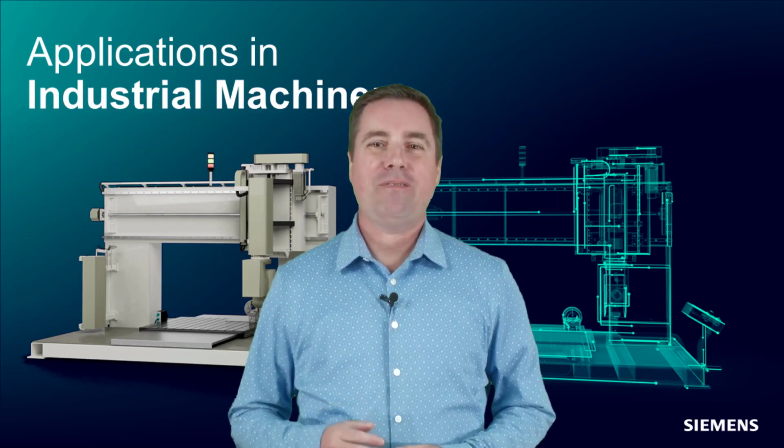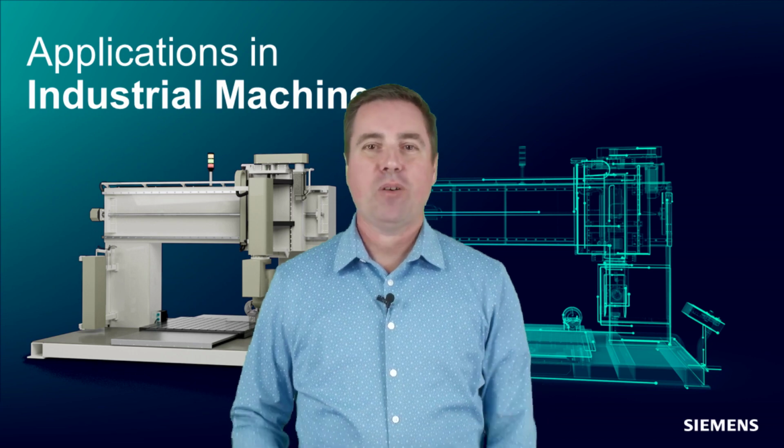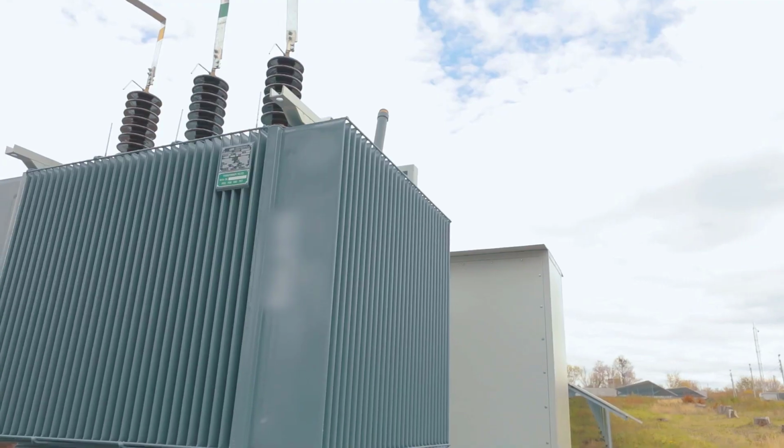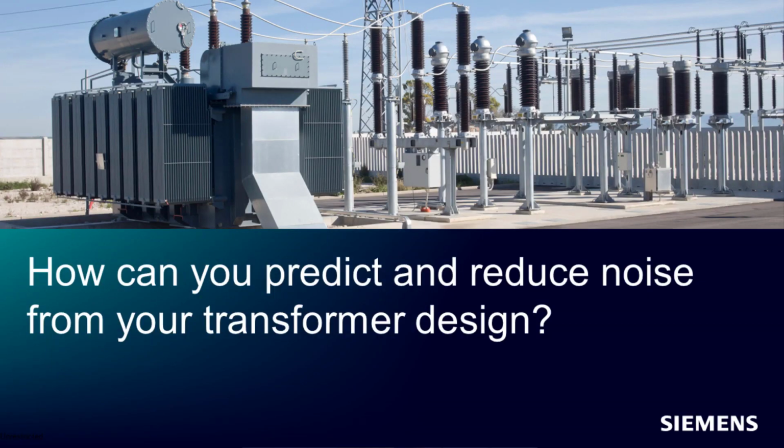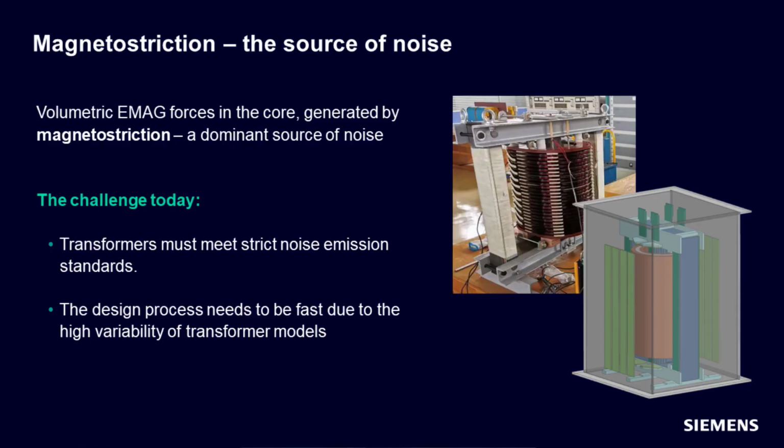Power transformers must meet very strict noise emission standards, mostly focusing on the so-called hum noise. Besides being an annoyance, this noise can give the perception of bad quality of the transformer. For some OEMs to qualify the eMag acoustics models for transformer development, the noise accuracy threshold is relatively high at plus or minus 2 dB from the measured results. Therefore, the power transformer design process needs to be fast and accurate because of the high variability of transformer models, depending on their application.